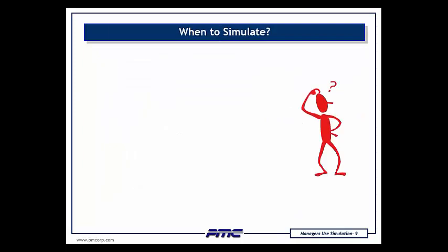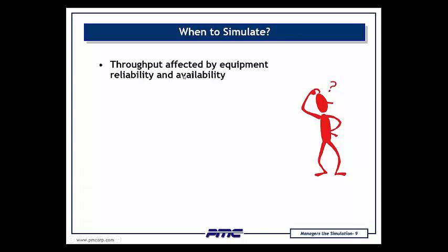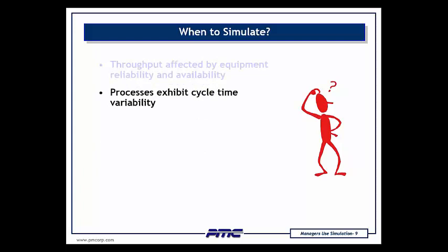Now, when to simulate? Very important one here: simulation can help address questions of equipment maintenance policies. For example, a piece of equipment is due for an overhaul after 10,000 hours. At 9,500 hours of use, it breaks down, so it's going to need repair. Is it better to pull the maintenance you were going to do ahead, or get it repaired, run it another 500 hours, and then do the maintenance as regularly scheduled? That question commonly comes up. Simulation can provide an optimum answer to it.